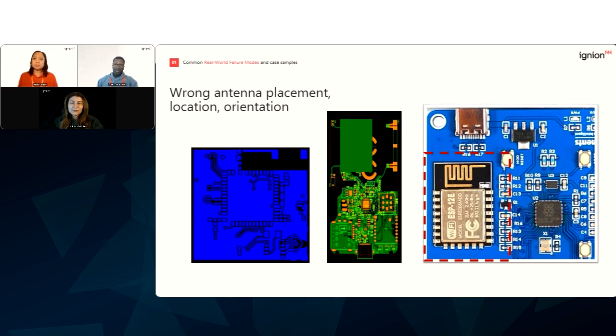So this sort of integration is not advisable, right? So you want to create some clearance or distance. If you could elevate that motherboard away from the antenna module, if you like, you could create that sort of distance that's required for performance. And this is obviously like a retrofit, because typically, what you're looking at here is an already certified module. And what you want to do is just plug and play with the bottom motherboard. But these quick fixes don't always work, right?